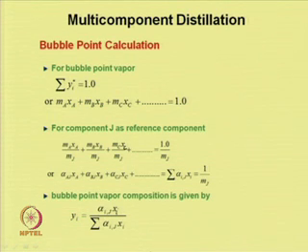If the liquid composition and total pressure are fixed, the calculation of temperature can be made by trial and error satisfying these equations, and its convergence is very rapid since the change of alpha with temperature is very slow. We will discuss this with an example.